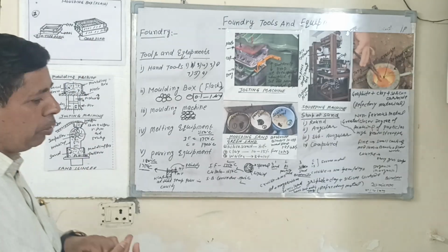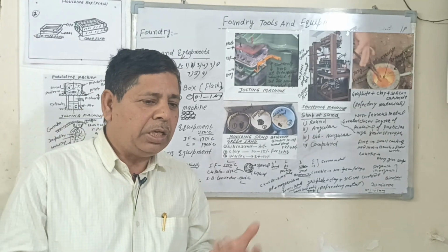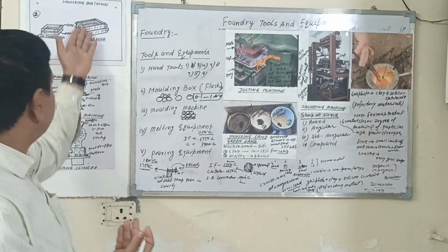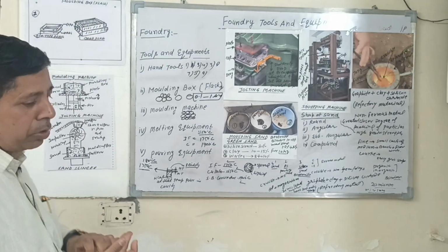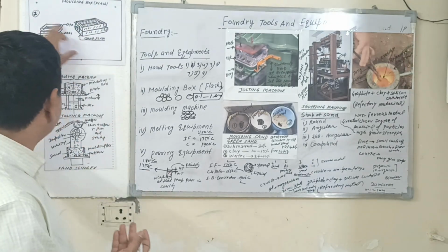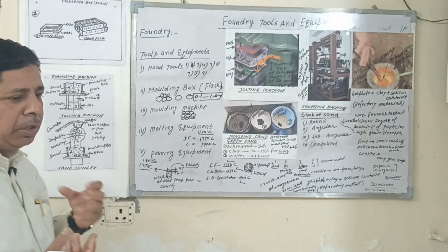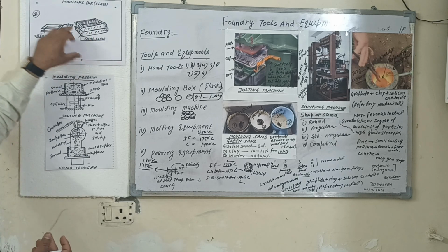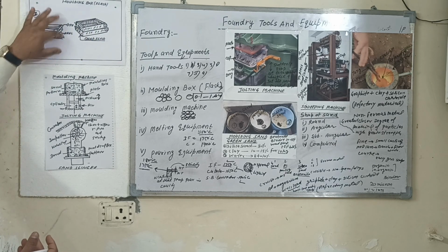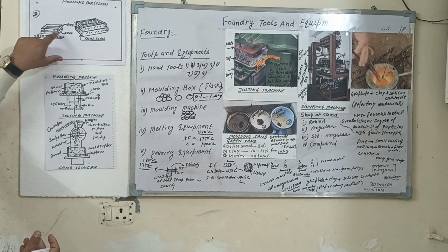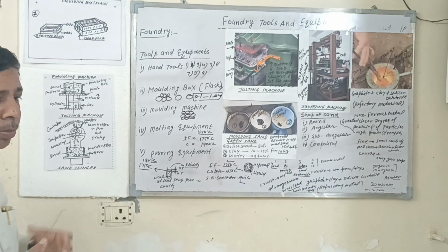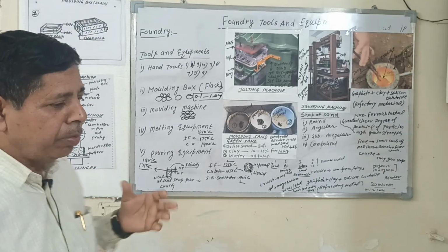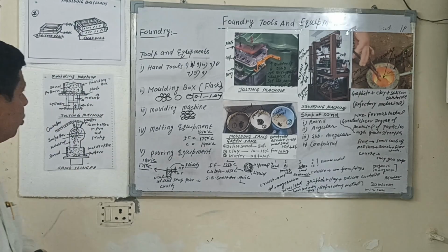The molding boxes are made of wood or steel. Wooden molding boxes are not used for mass production, while steel metal boxes are used for mass production, because in this process the adhesive force is not provided here. The adhesive force cannot withstand the use of wooden boxes again and again in contact with the sand. So metal molding boxes are used for mass production.